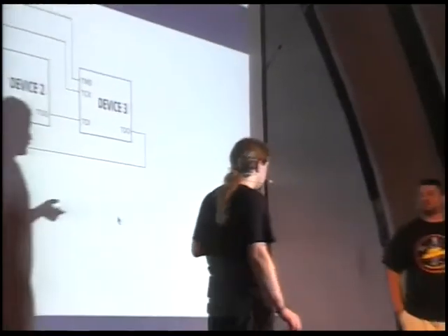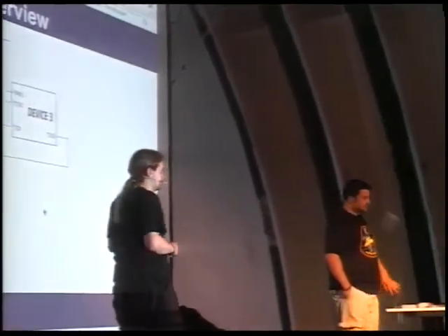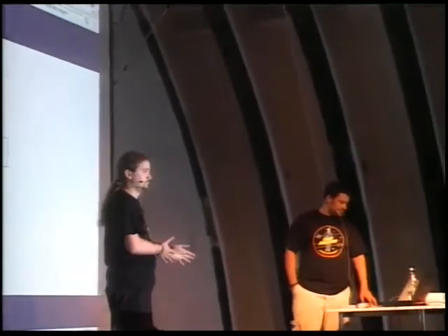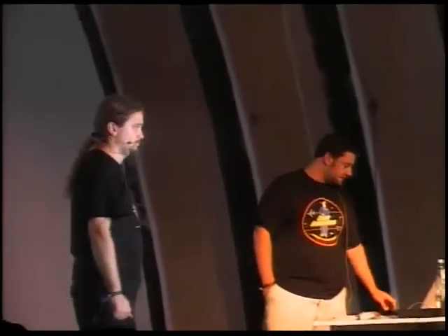There are open source tools available that will allow you to do manipulation via JTAG port. Depending on what device, there might be specific tools; routers have their own. I think there's one called HairyDairyMaid, yes, which is for debricking a router via JTAG port, and it's a very primitive implementation of the JTAG, but it does what it's intended to do.